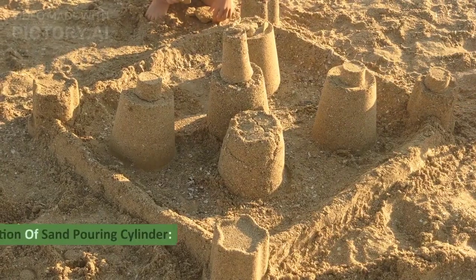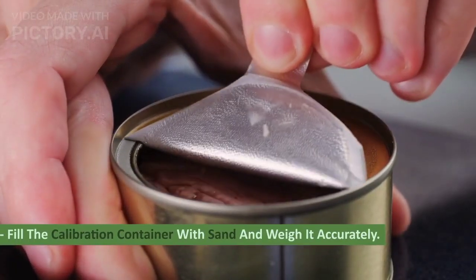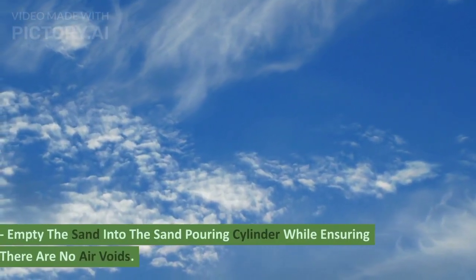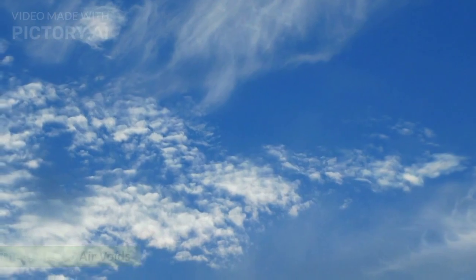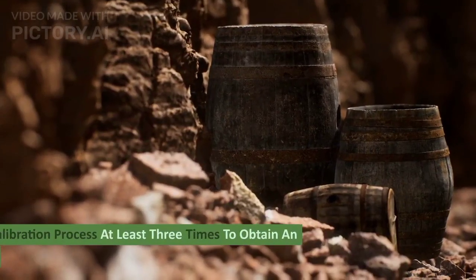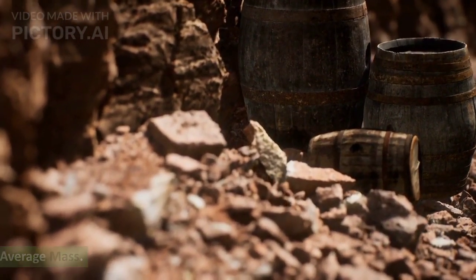2. Calibration of sand pouring cylinder. Fill the calibration container with sand and weigh it accurately. Empty the sand into the sand pouring cylinder while ensuring there are no air voids. Weigh the sand-filled pouring cylinder and record the mass. Repeat the calibration process at least 3 times to obtain an average mass.